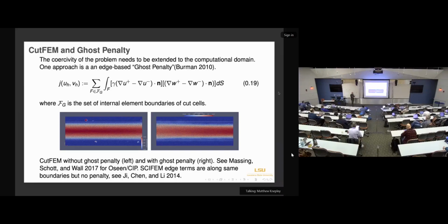He's using uniform order on pressure and velocity space. So P1 for pressure, P1 for velocity. It doesn't have to use mixed elements, and he doesn't have to use internal stabilization, and he recovers second order convergence for both pressure and velocity for that scheme. So it's an interesting approach. Particularly if you're going to be doing this anyway because of interfaces, you could use that scheme because you're going to have those extended stencils anyway.